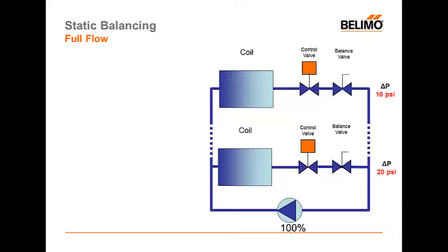This means that the water flows out of the pump and directly into that first branch run. It goes through there, and then that first branch run is closest to the pump on the return, and therefore the return water is at its lowest pressure point there. So I have high pressure water coming into the first zone and low pressure water coming out of the first zone, and therefore I have a very high differential.